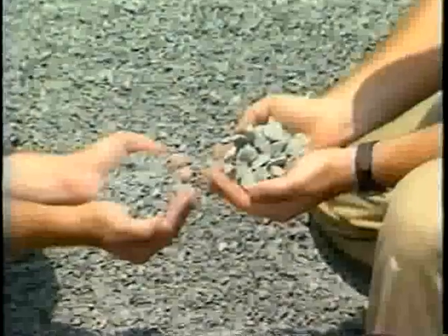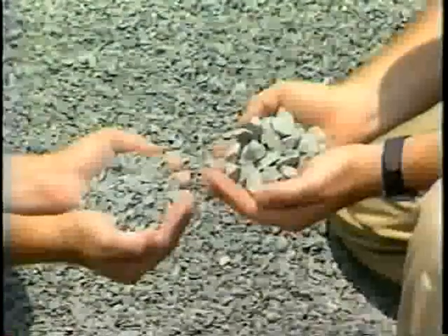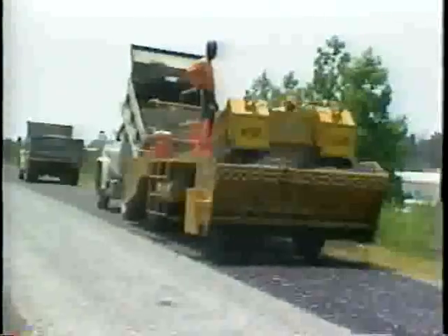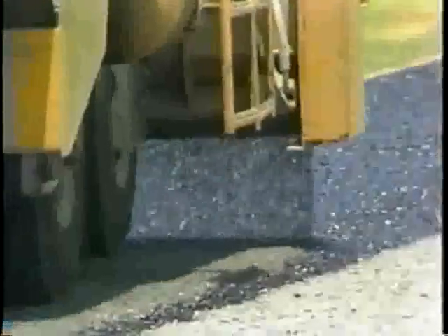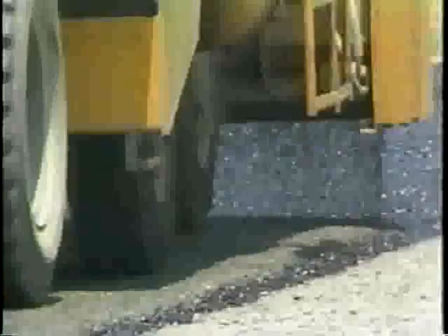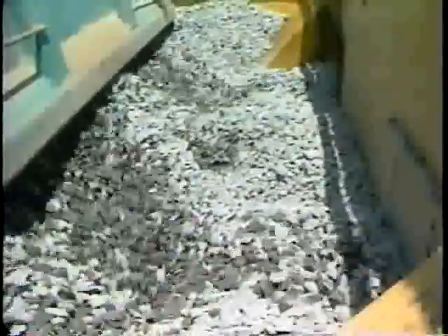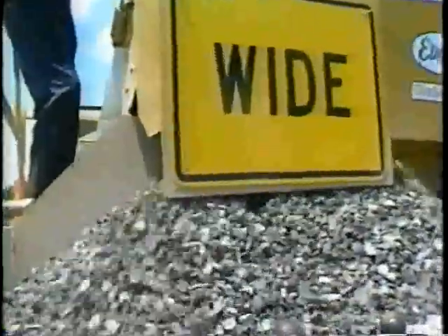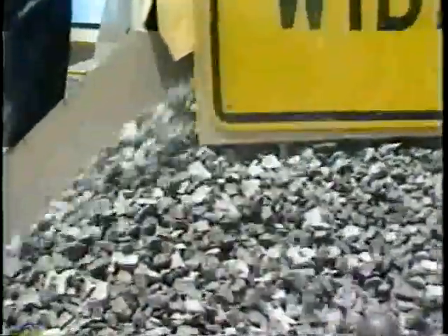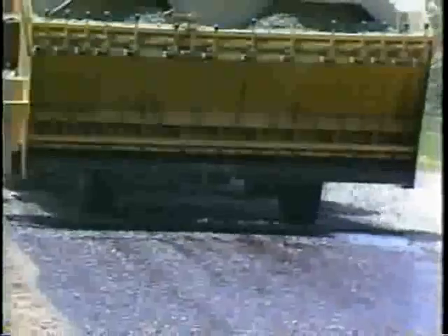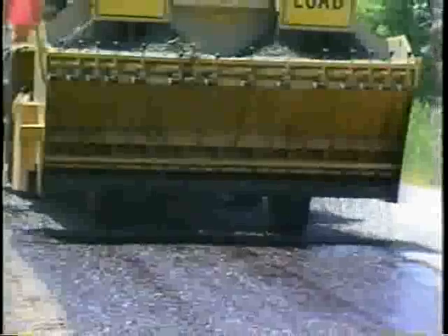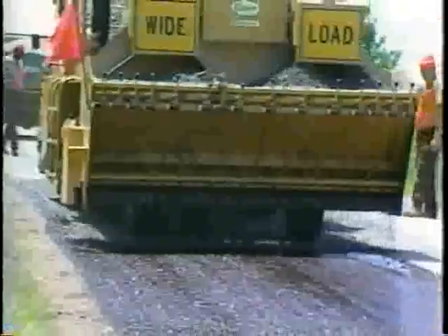The size and type of aggregate used depends on several factors, including the number of layers being installed and the type of emulsion being used. Aggregate used for chip seals should be cubical in shape and as near to a one-size material as is economically feasible. Do not use a graded aggregate, as the smaller sizes may become immersed in the asphalt film.